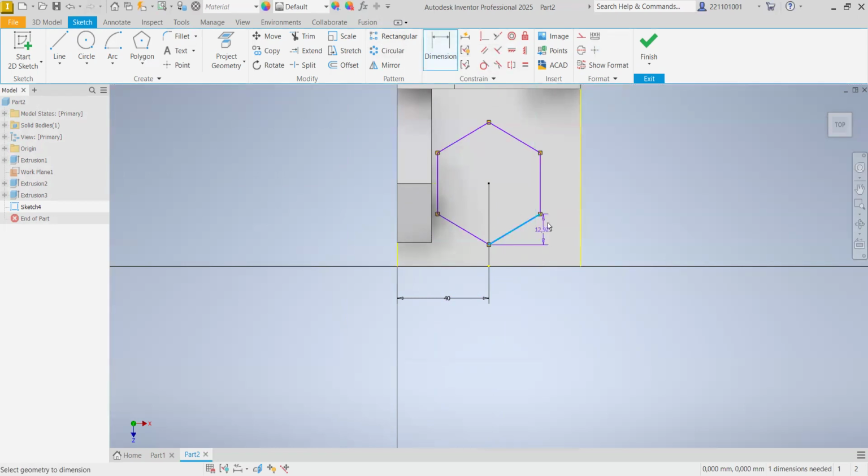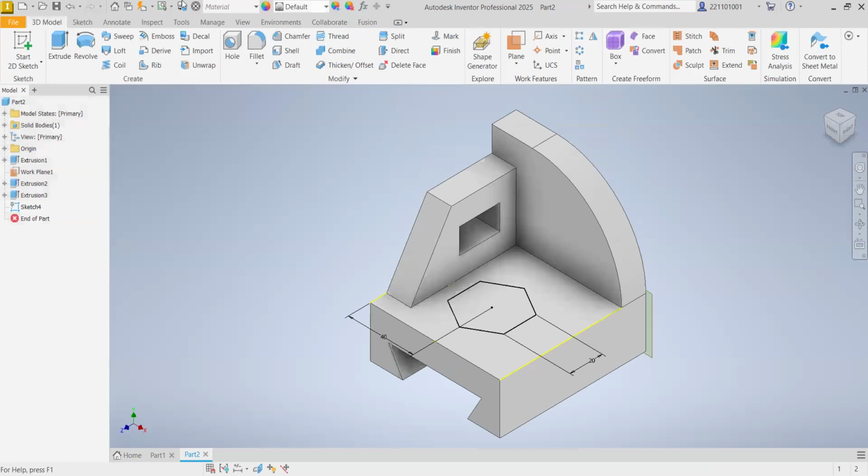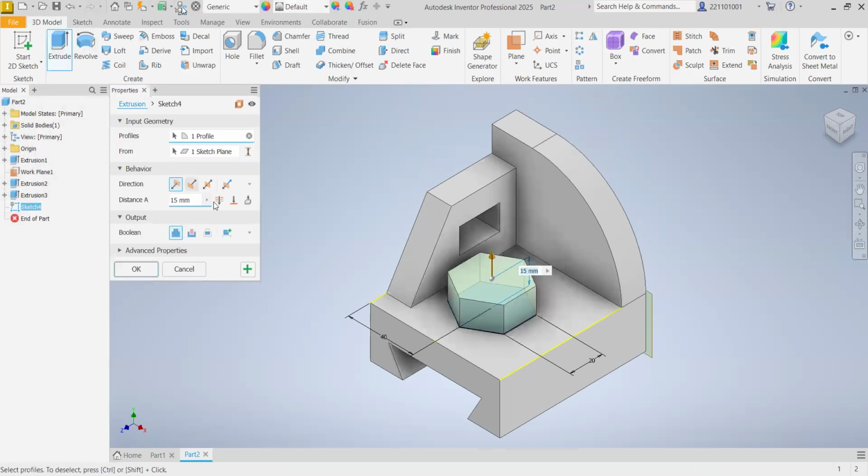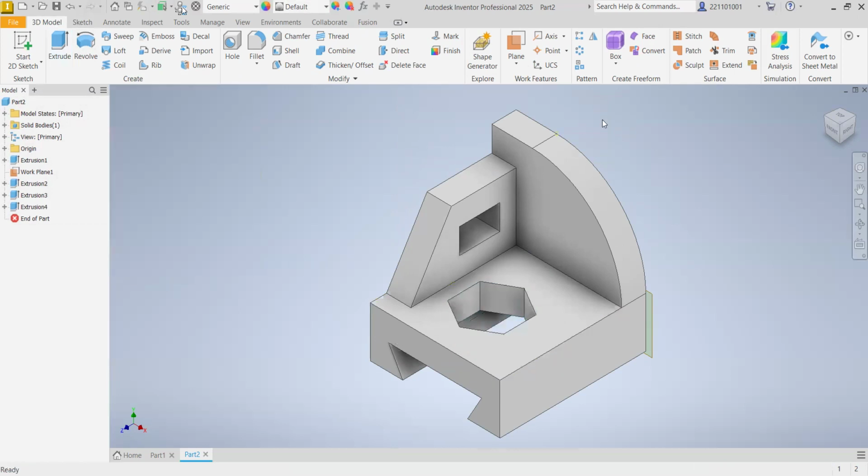And then we are told that this side of yours must be 20 millimeters. And then down. Extrude the cut going down, the cut distance, you're cutting through all, finish. Then you can slightly...